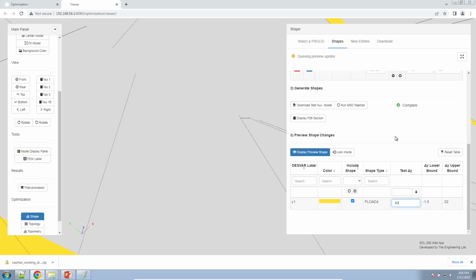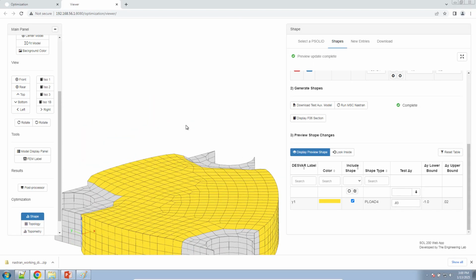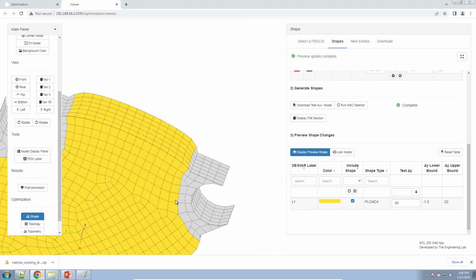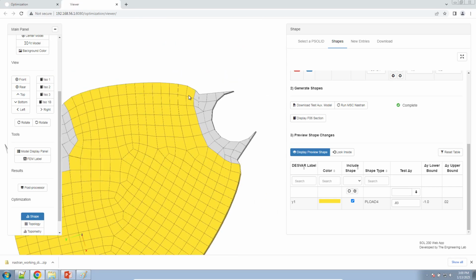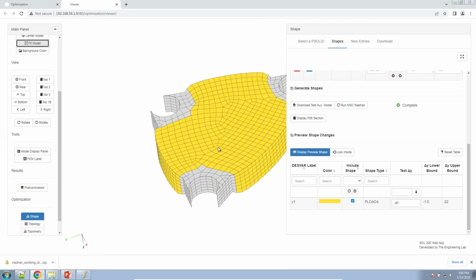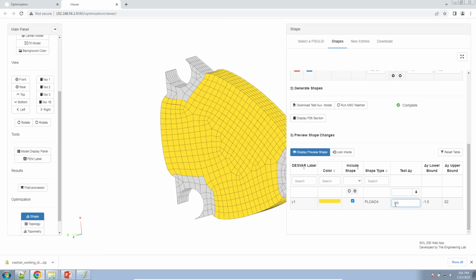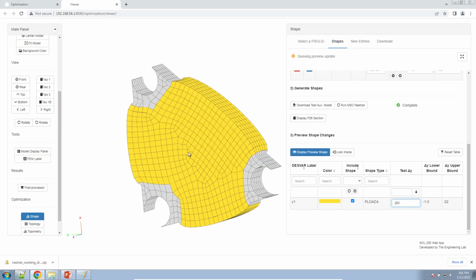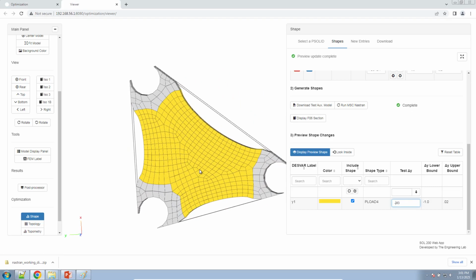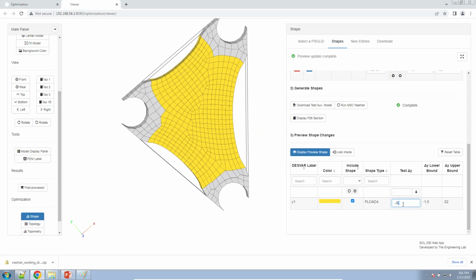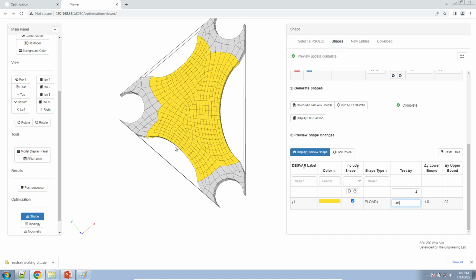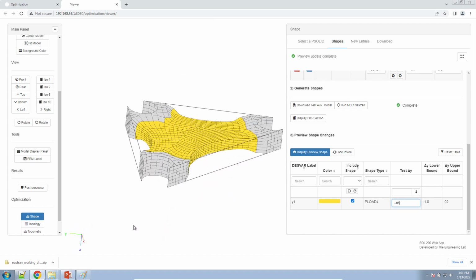Let's make sure the test value here is a little bit more manageable. Okay, so right now we're looking at the shape when it's being expanded. I'm just glancing at it, making sure nothing is too distorted. Okay, this looks okay. And now let's contract this by negative 0.03. Now the question is, does it look distorted? When I look at this, it looks okay. Now let's reduce this a lot more. Let's try negative 0.05. Okay, the elements do not look distorted.